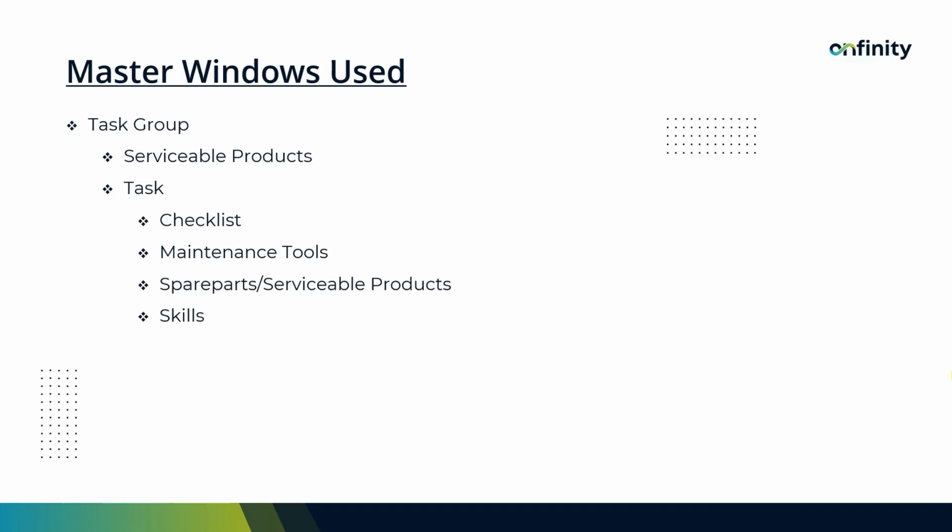Tasks are the activities or the jobs that a technician or a resource has to perform when going to a site, a customer site, or for a plant maintenance case. These tasks could be multiple against one task group, so one task group can be used for the categorization of the tasks. For example, for the preventive maintenance of machinery, there could generally be 4 types of tasks: cleaning, lubrication, retightening, and inspection. We can create 4 tasks into one task group, and we can assign the task accordingly.